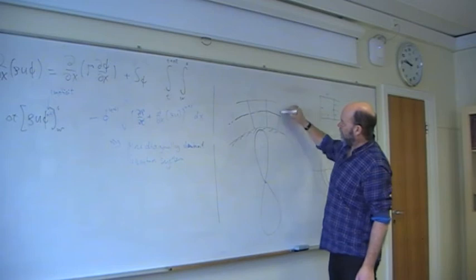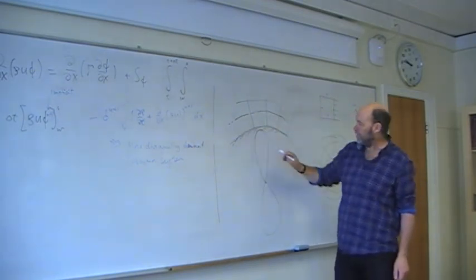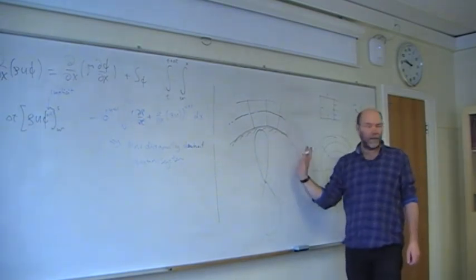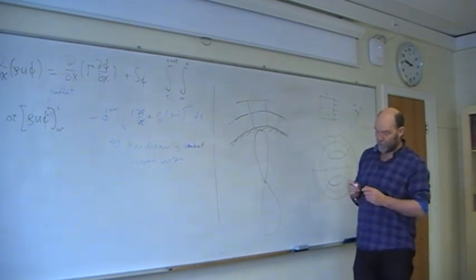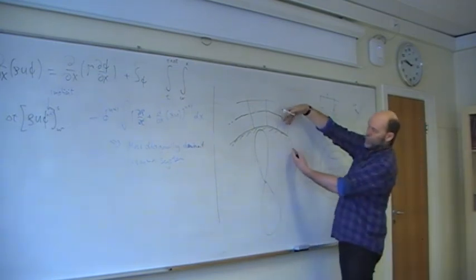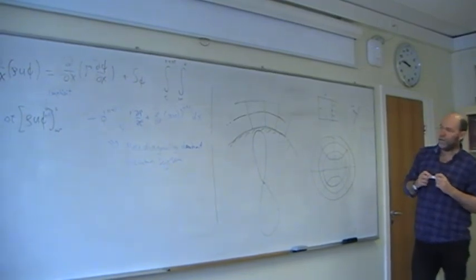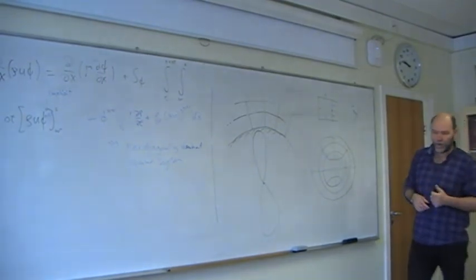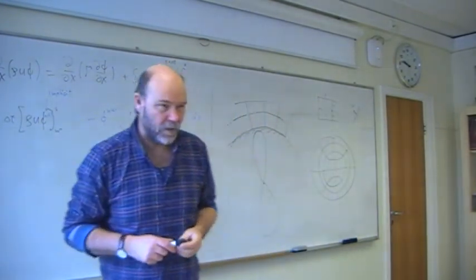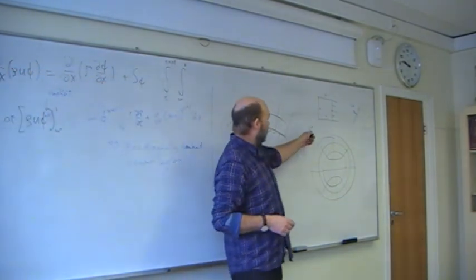So that means you will have sort of a sliding mesh line here, where you can have cells which now will have any orientation in regard to the fixed mesh. But of course then this type of interpolation will be quite crucial when he slides. But that is how you can handle moving parts in your problems. Not easy, but yes, possible, if you do such simple problems like this correctly.